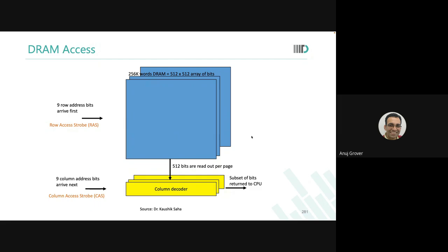So let us say one high energy particle hit your DRAM. That high energy particle spoiled 30 bits. But those 30 bits all belong to 30 different words, and in all those 30 words, only 1 bit is wrong. So single error correction, dual error detection code still works.